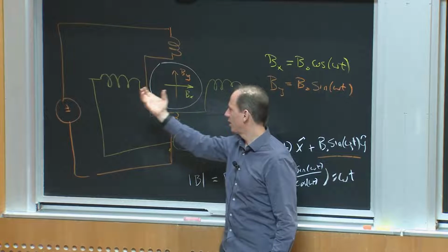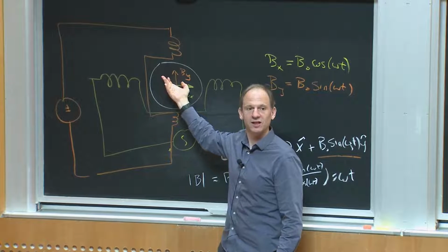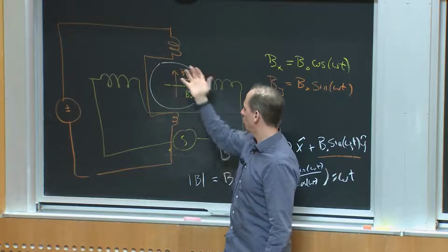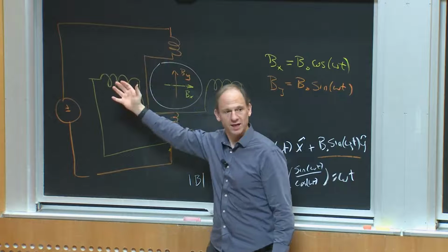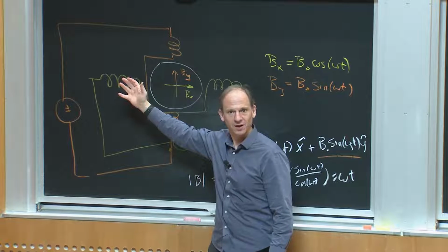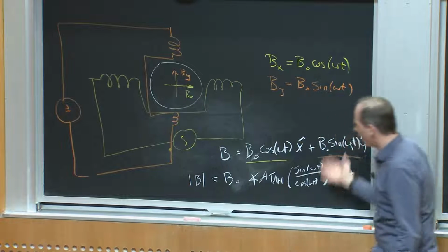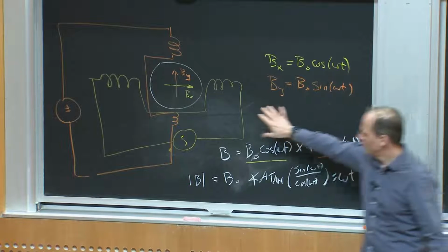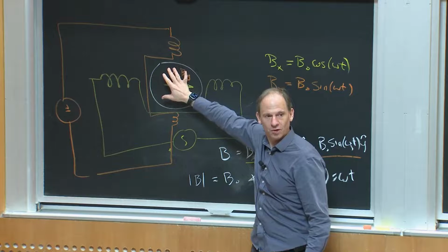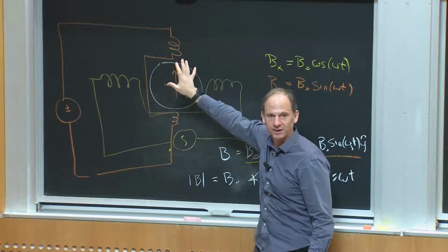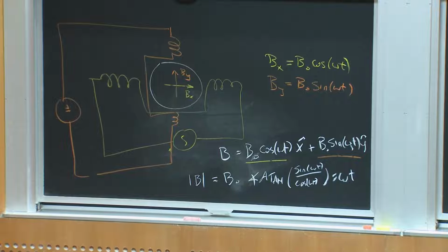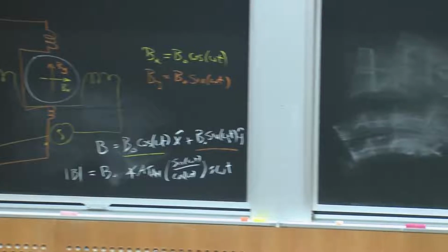Okay? So then if I put some sort of salient ferromagnetic material in here, or I put a magnet pole pair in here, I could make that rotate in space. All right? So this concept of using spatially and time orthogonal signals to generate a rotating magnetic field, the first person who really made it practical and used it for practical purposes was Nikola Tesla, and that's the first thing that made him famous.